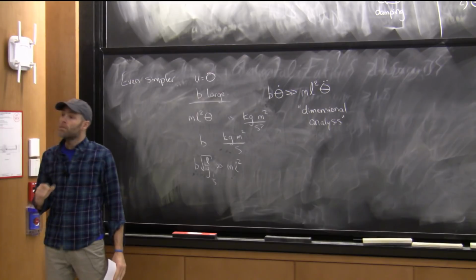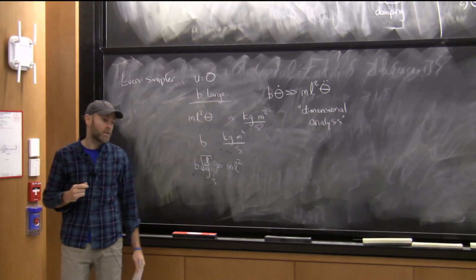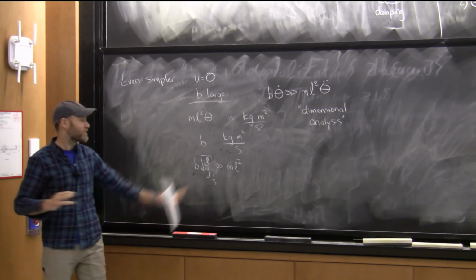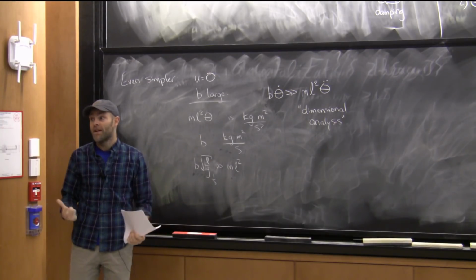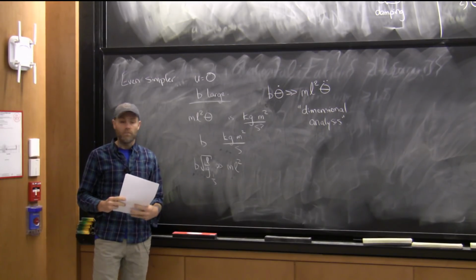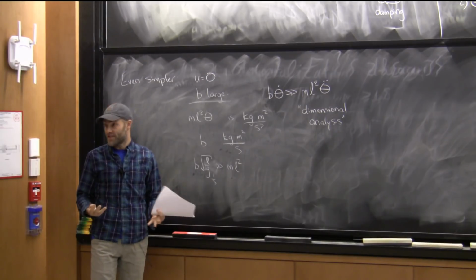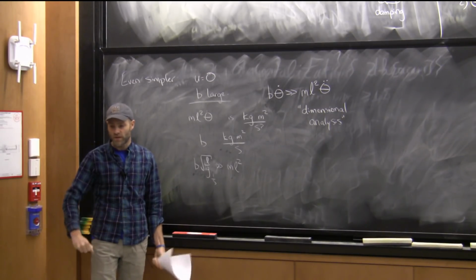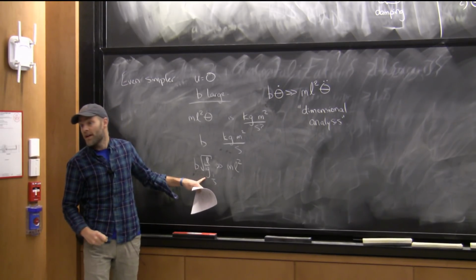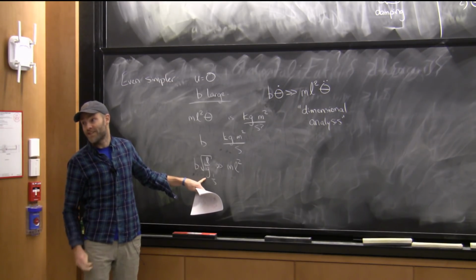But for an arbitrarily complex system, how do we know what to pick to make the units match to make this type of statement? Yeah, no, there is an art to it. The part that dimensional analysis tells you is you've got to get the units right. But in picking the units, there has to be some characteristic motion that you're trying to capture, right? If I was trying to capture something totally different, like the response to super high frequency torques, then this might be a bad choice. So I don't have a general solution for all cases.